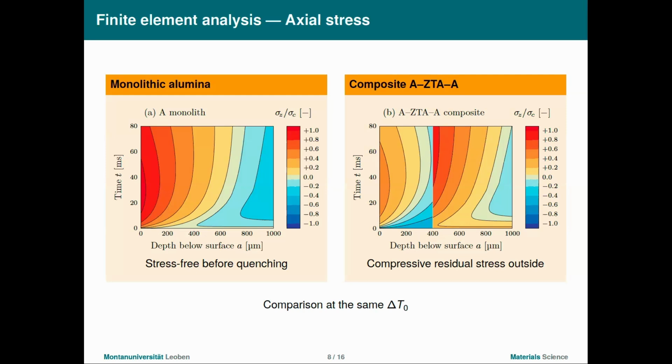monolithic alumina, and on the very left you have free surface. As you go up from the bottom, we follow time in milliseconds, and you can see after approximately 30 milliseconds, you reach the most critical conditions with respect to the strength, but that doesn't mean anything, because also with the increasing time, the boundary between the compressive region and the tensile region is changing. After much more time than, let's say, 10 seconds, the region is deeper, where the cracks are under tension.